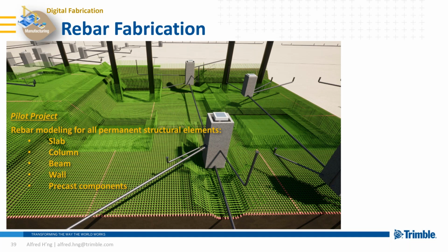After the first step is done, we move to the next step. The second step is we extend this information to our external parties, our engineer, our rebar scheduler, our subcontractor, or our rebar fabricator. They will make use of the model, go in there to check, review, query, and extract the information. As the second step, the rebar information, the first time we export it as base information only.